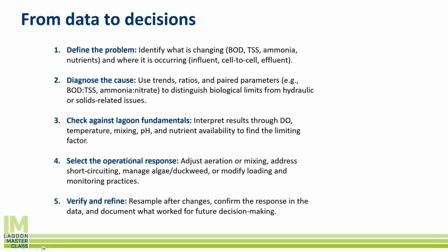And then look at my monitoring practices. When am I sampling? How often am I sampling? Grab samples when maybe a composite sample is more appropriate, or vice versa. And then verify and refine. So resample these after we make changes, confirm that there's a response in the data, document what you've been doing. You have to take notes every time we make these operational changes.